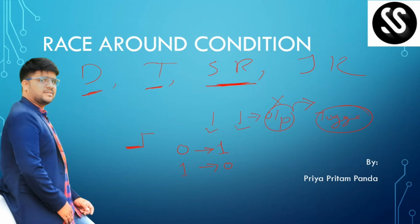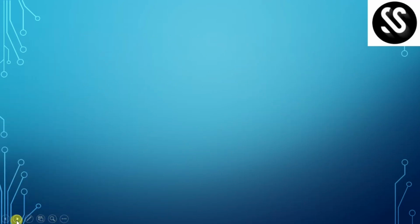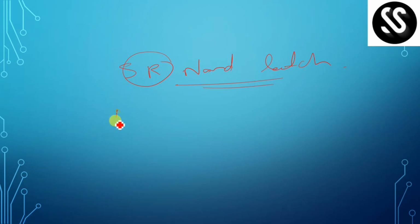A flip-flop can be designed using a latch, a NAND latch or a NOR latch. The race around condition basically comes in the case of the NAND latch. So whenever you have an SR NAND latch used to design a JK flip-flop, right? Let's say you have a NAND gate over here and another NAND gate over here, and here is the S input, here is the R input.